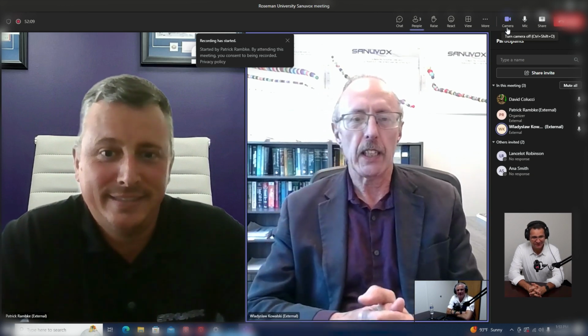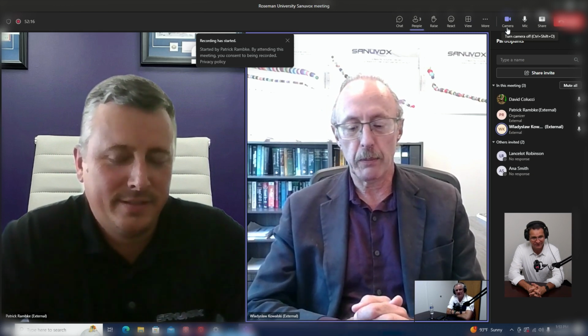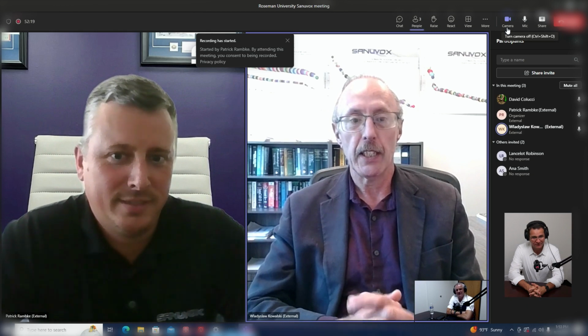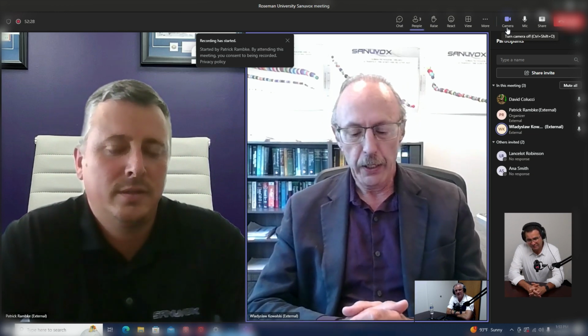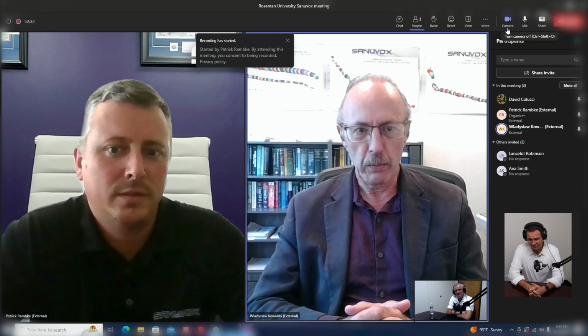Upper room systems can only create a UV kill zone in the upper room. That kill zone cannot be in the lower room because it would probably exceed NIOSH threshold limit values for UV. Those are set very strictly by NIOSH, OSHA, ACGIH, and others. Therefore, anything below the upper 1/5 of the room has to be free of hazardous UV.